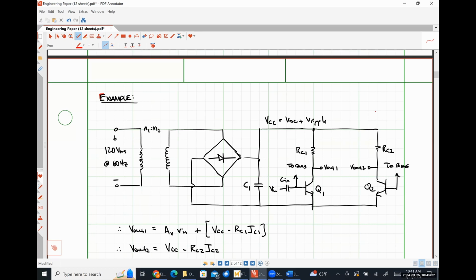Because remember that if it dips too low, we're pushing our transistor out of the forward active region and into the saturation region. So if we were dealing with, say, 5 volts, and we had plus or minus 1 volt of ripple, that's pretty darn gross. If we were dealing with plus or minus 0.1 volts of ripple, that's not going to have a huge effect.